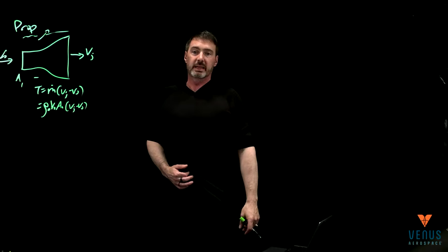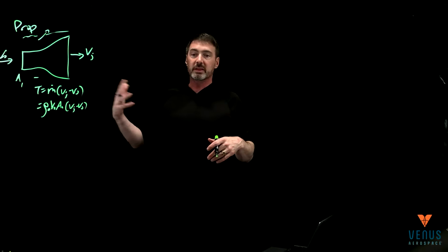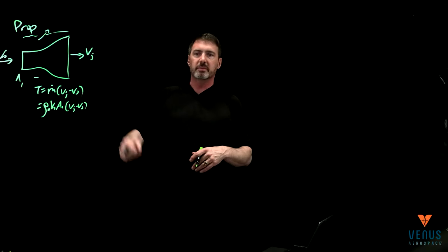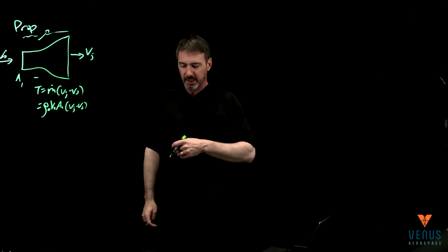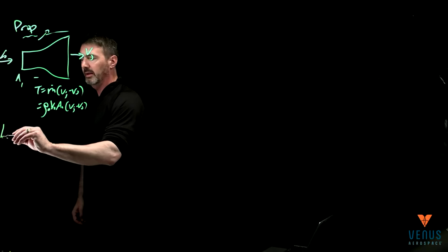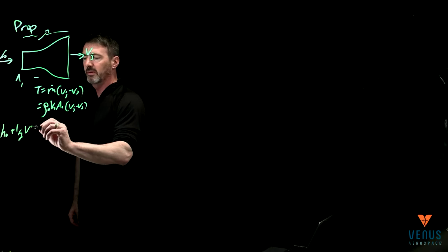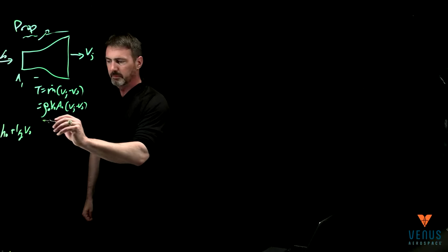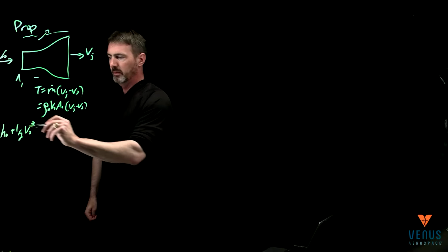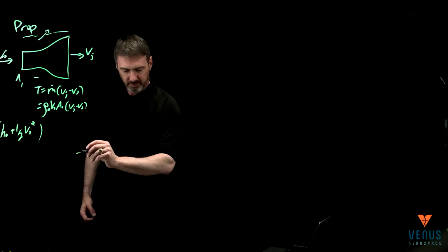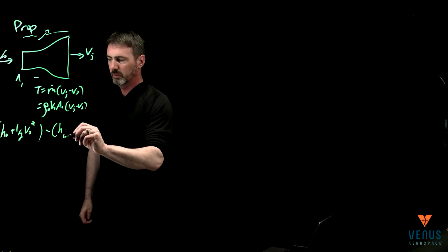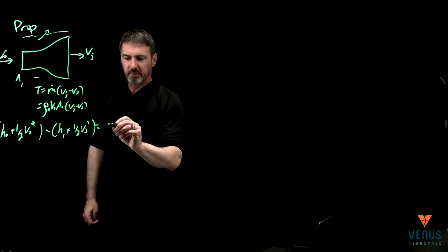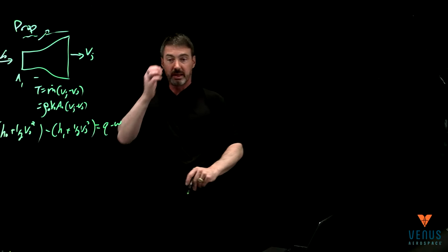First, we want to say that mass is conserved. That's why I was able to split the m dot out. From an energy point of view, we have the enthalpy plus 1/2 V0 squared, the enthalpy plus the kinetic energy. Then H1 plus half V1 squared, and the difference between the two is the heat minus the work.